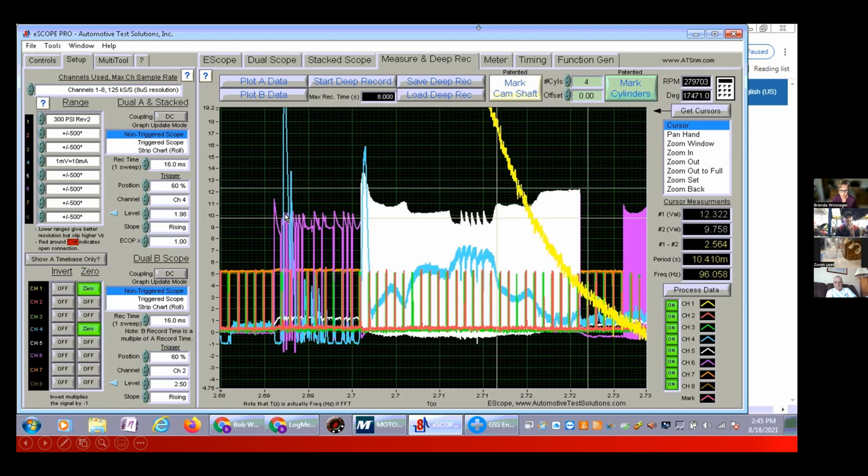And then we'll dive into what the answer is and how we located and identified what you're seeing on the screen. What do you guys think this blue current activity is in the purple phase that doesn't really match this one in the shorted phase? Any ideas? Three phase. Bad diode. Oh, that's a great guess. A bad diode. Okay, anybody else?